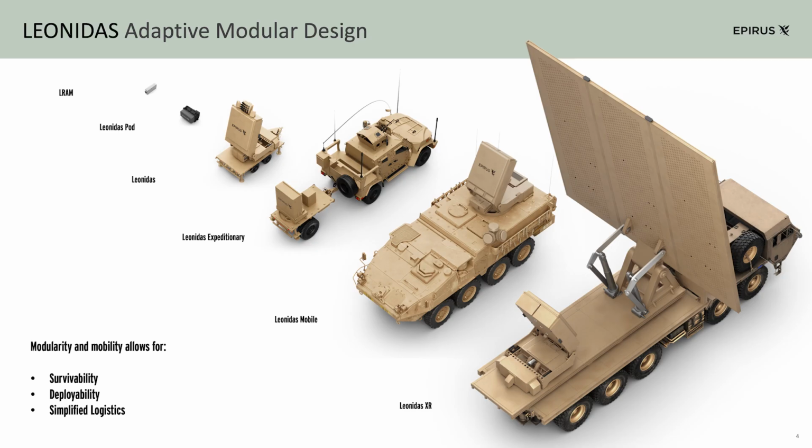And you can see the LRAM at the very beginning. It's very tiny. It's a line replaceable amplifier module. And inside of that is where all of our RF amplifiers live. And each one of those is designed in ADS. So we have the discrete transistors custom made for us, and then we design the amplifier modules around them so that they can fit into a form factor that is very easy to replace.